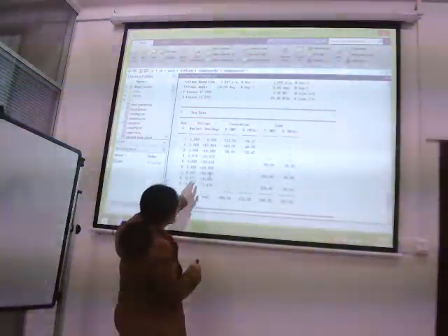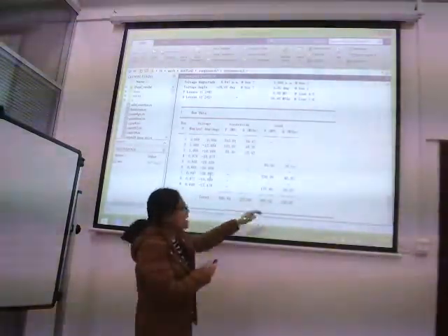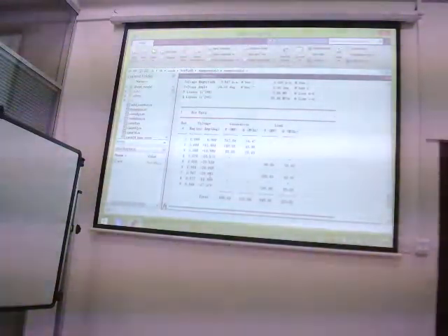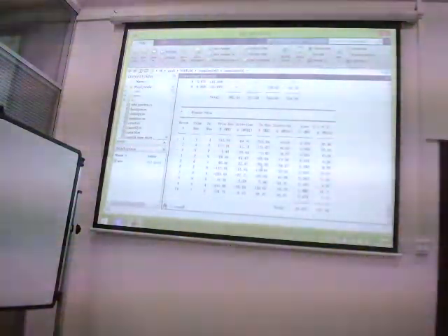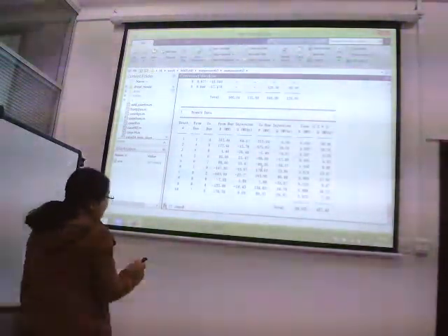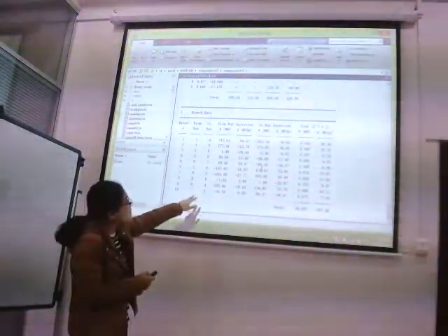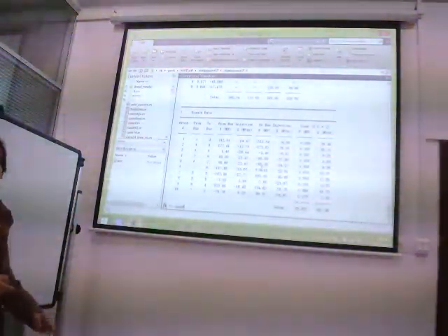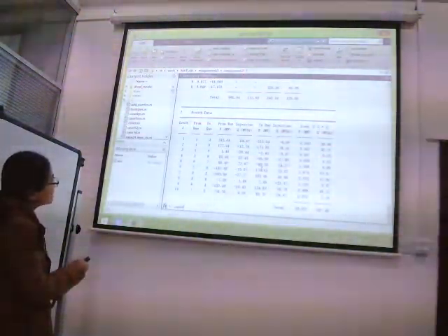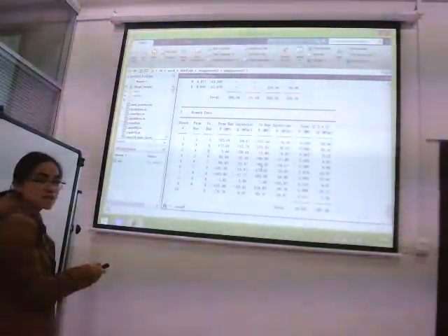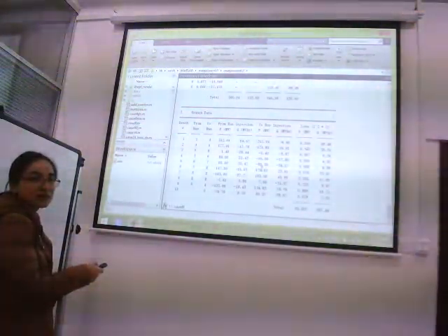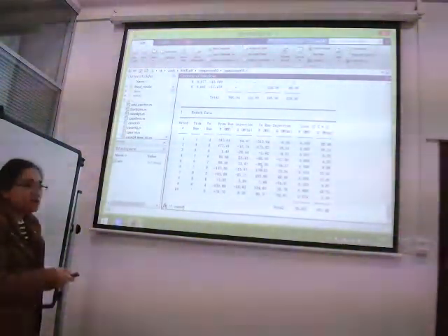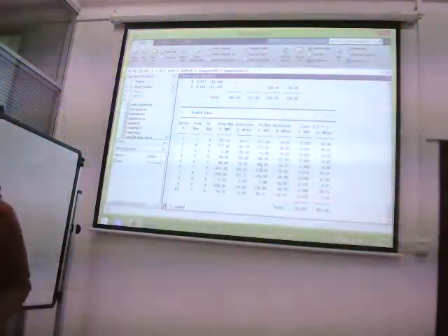Okay? So for the load demand, bus 7 now has the maximum load demand. The load demand here is 330 megawatts. Here we can see the branch data, because of bus 7, we can analyze which loss is the largest for the 10 branches. For branch 4 to 5, the loss is the largest, 5.558. And for the branch bus 7 to bus 5, the loss is also large, 3.725. Let's see why.